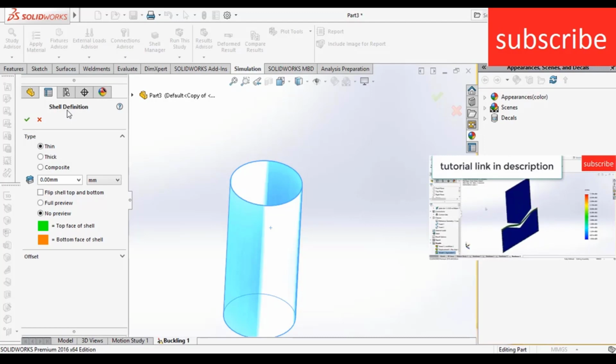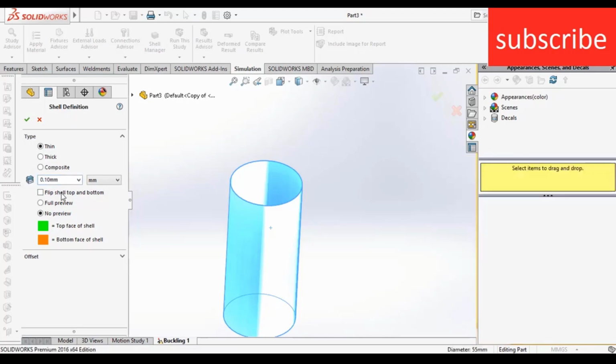If you get a choice between shell definition and a solid model part, prefer shell definition. Remember, shell definition is only chosen when you have a thin part, not otherwise. Here I will enter a value of 0.1 mm because the thickness of the cylinder can is very small. It is a thin cylinder, so I am selecting thin. It is not thick, it is not composite, it is thin. Now click OK.